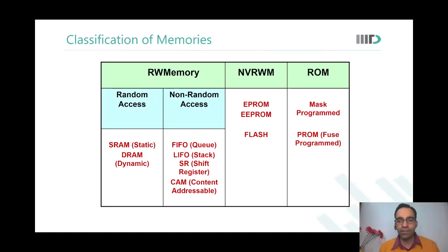Faisal, you have your hand raised. I just want to clarify a statement about shift register and FIFO. Due to latency, we are using shift registers, so you could also use a FIFO there. That's why I was confused, sir. Yeah, you could also use a FIFO there. If you just need to have a few words, then shift registers are more area efficient than FIFOs. But if you need more words, then FIFOs are more area efficient.